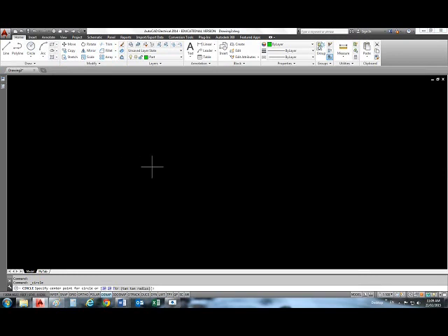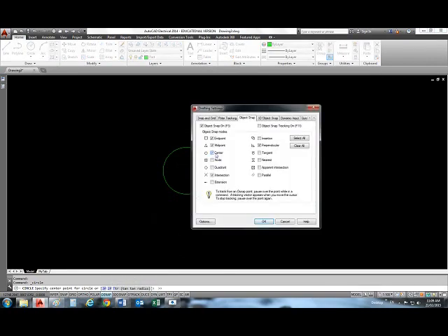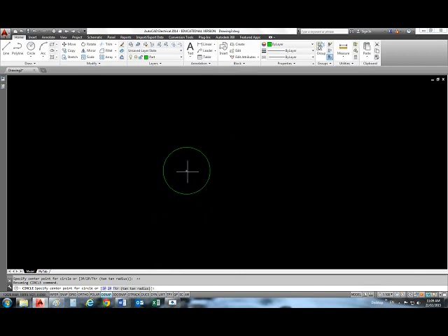It's not important where you start. And 25.4 for the internal, double click, and then the circle command again, or space bar to repeat the same command. Make sure your center snap point is turned on. So right click, settings, and then center, OK, go to center, and this time 50.8, enter.